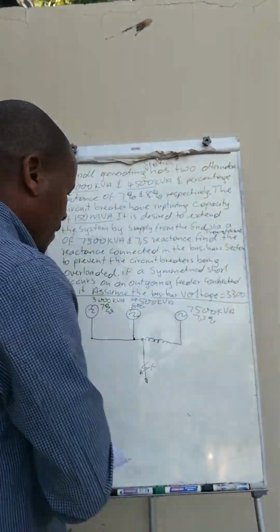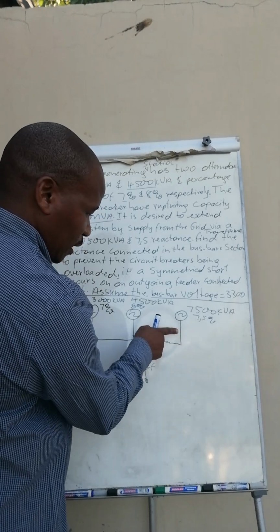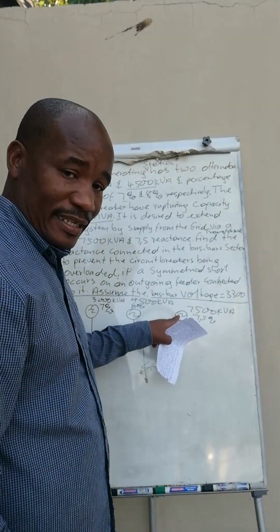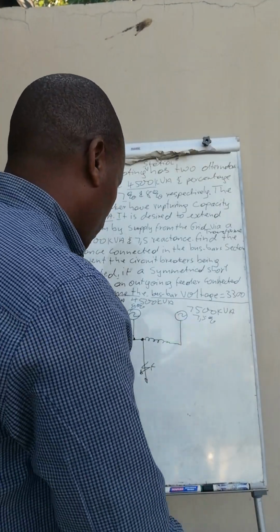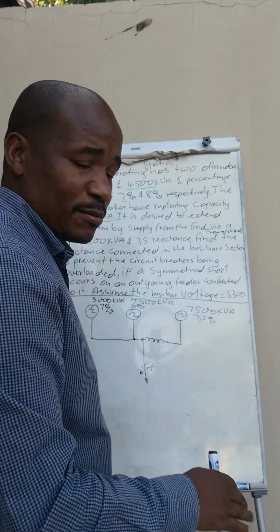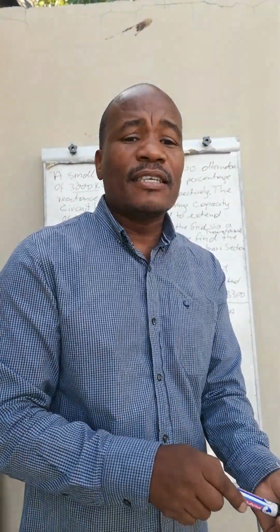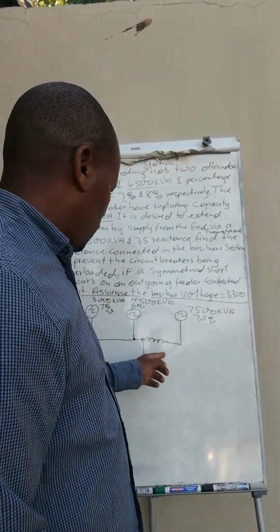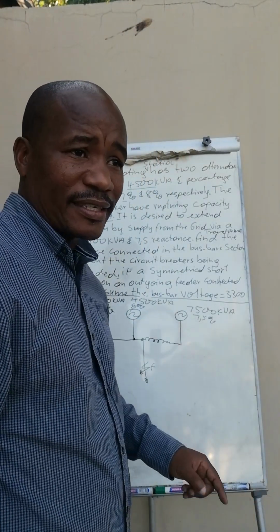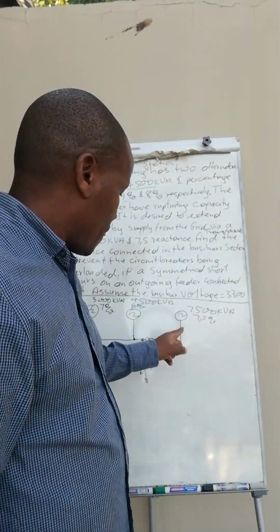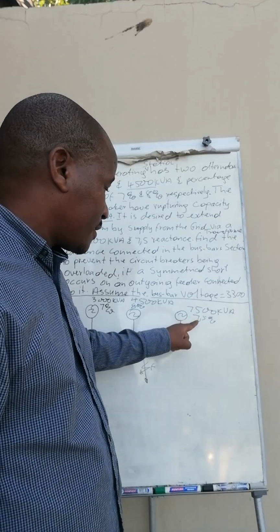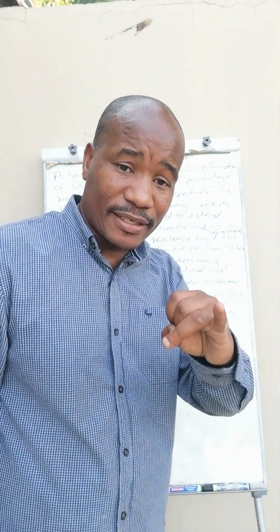You remember yesterday we showed that you can connect a reactor in series with the generator, and they can also be connected in the feeders or in the bus bar. In actual practice, normally they don't connect reactors in series with generators for two particular reasons. First, the generator has sufficient internal reactance to protect itself from short circuit.